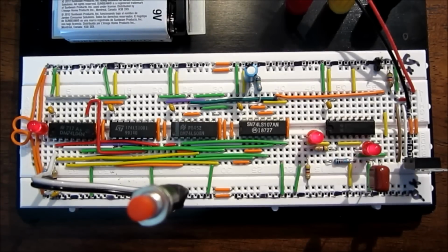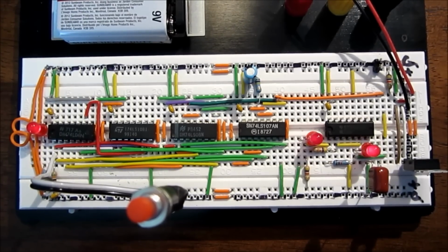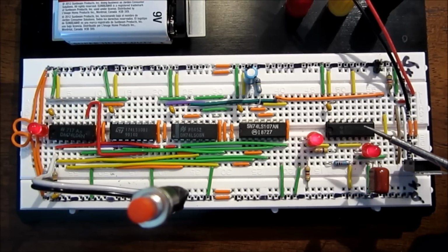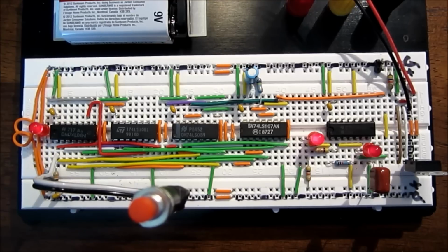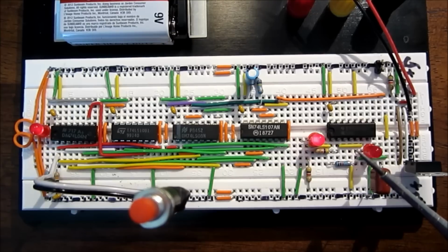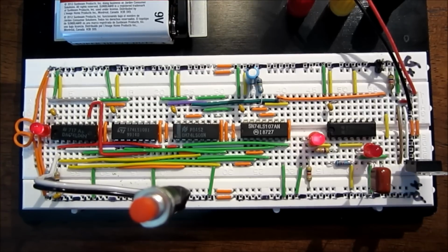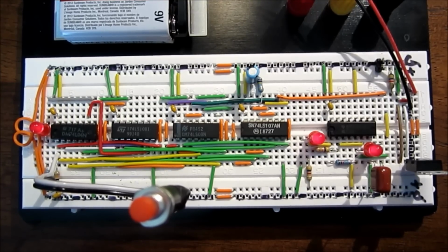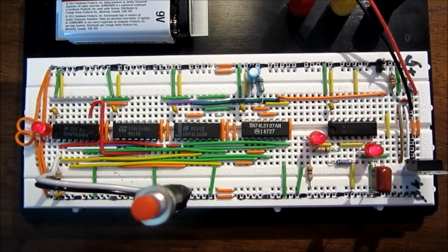Here's the breadboard for the one switch off on Finite State Machine. It uses 5 chips. This first chip over here, U1, is a 556 timer which incorporates 2 555 timers. These LEDs that are flashing right here are the T1 and T2 period off on of the left side of the chip, the first timer. Now they might look like they're oscillating in and out, but actually they're steady. That's just the interplay between their flash rate and the scan rate of the camera.